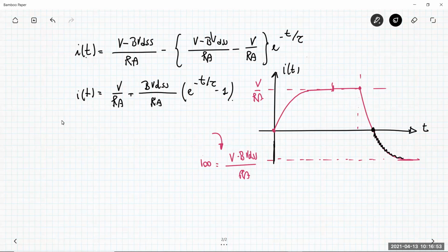It becomes a real open circuit. So here the MOSFET has a behavior which is the real situation, and this is the mathematical abstraction, if you want. The current cannot go negative. When it reaches zero, it becomes null. The MOSFET will be open.